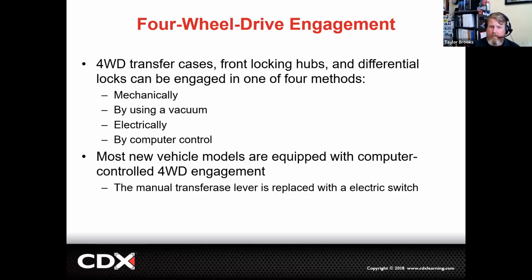As stated before, when we shift a transfer case into four-wheel drive, it doesn't necessarily mean that we're sending torque to the front axle. Actually, selecting four-wheel drive usually will also require us to go through and lock the front differential axle shafts or the hubs. First, let's talk about how we're going to engage the transfer case.